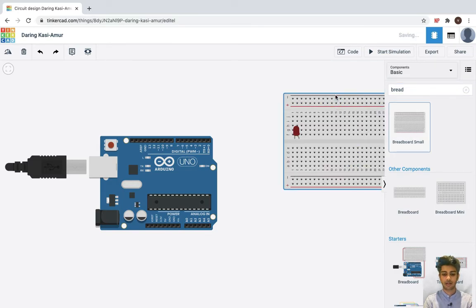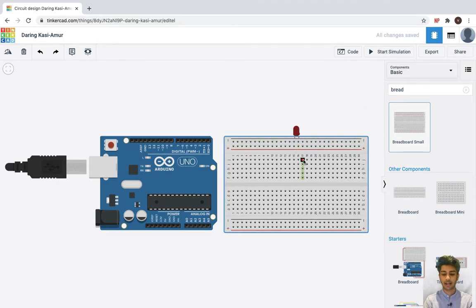Basically this is a breadboard, and all these connections on the inside of the breadboard, the green lines, indicate that all these connections are common. That means if I plug the LED over here and a wire over here, they are connected. Similarly, on the outside, these lines are common, which means that if I supply, let's say, 5 volts over here, then I'll get 5 volts over here as well. This is really beneficial in prototyping. You can attach all your components of the circuit over here, and a breadboard is typically used by all activities in electronics for prototyping. So let's get started.